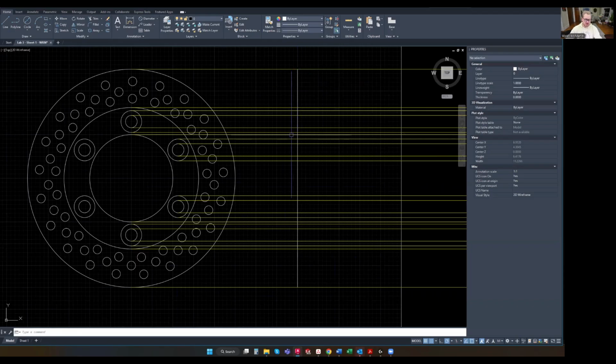So you can drag and snap to 90 degrees and type 5, enter, or you can just drag up to where the perpendicular icon appears, the little L, and snap it to this top line. And after that, I'm going to turn off my grid snap at this little button right here. And I'm also going to click the snap drop down and turn off Nearest. It gets in the way if you don't need it.